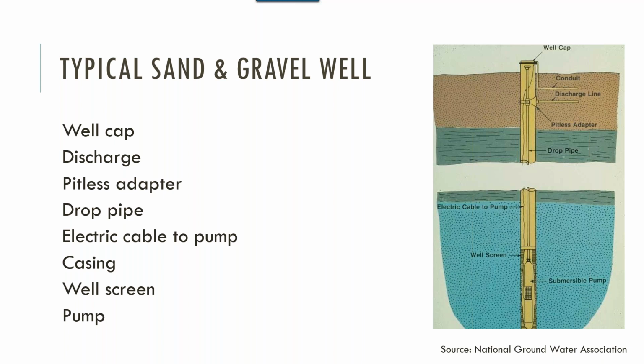So if you have a 200-foot well, typically the lower 10 feet or less, 4 to 6 feet typically, is a well screen. So that means water's coming in the well from 200 to 194 below land surface, let's say, or 190 to 200. So that means there's 200 feet of material that anything at the surface has to get through to get down to your well and get in your well.